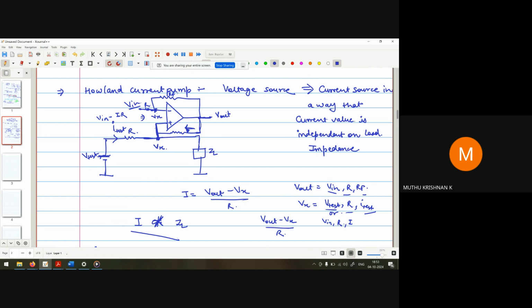And sir, this V test with the series resistance R, because it is the internal resistance of V test, will it be changed into a current source with a parallel resistance R? Yeah, you can change it. Source transformation. V test with the series resistance R provides the current source I test. Now in place of V test and R, I can use I test and R in parallel.